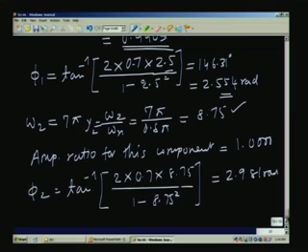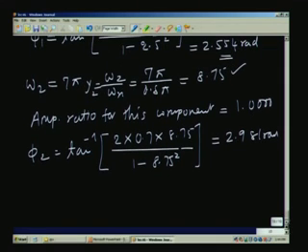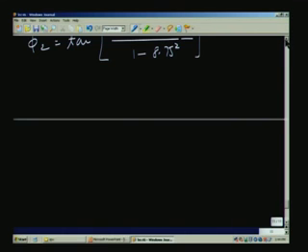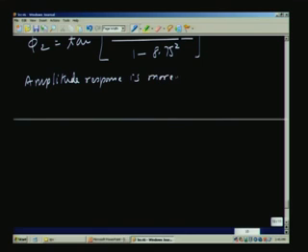So, we have the amplitude ratio for the first case as 0.9905, and for the second wave as 1. Therefore, there is a very small amount of distortion, because the first part is going to be 1% less than the input amplitude. To that extent, there is a small impact on the value. So, amplitude wise, the amplitude response is more or less faithful. That means very small change in the first component, and the second component is more or less preserved. However, if I look at the phase relationship, the output phase of the first component is different from the output phase of the second component.